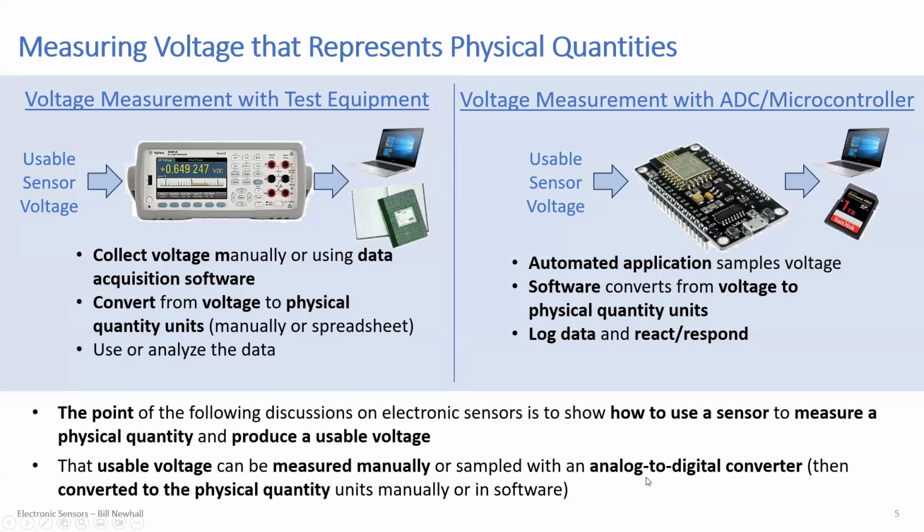You've seen how you're sampling time between blade crossings, and you have a counter in microseconds, and then you're converting that to a rate that represents the RPM of a propeller in revolutions per minute. Okay, but it all starts out with a sensor.